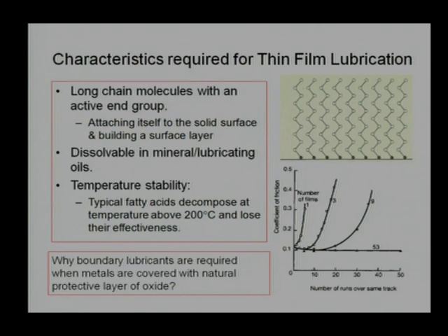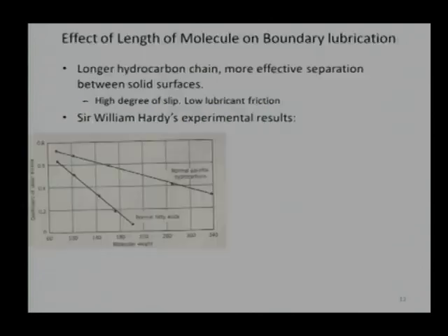So boundary additives and boundary lubricants are important, even though there is a protective layer of oxide, because the oxide layer may be fractured by some additional load. We want to increase the load carrying capacity of the surface, and in that case we require boundary additives. If we are operating surfaces at low load conditions, then boundary additives or boundary lubrication may not be required, because the oxide layer itself will work as a boundary lubrication mechanism. There are some results available from Sir Hardy's experiments.